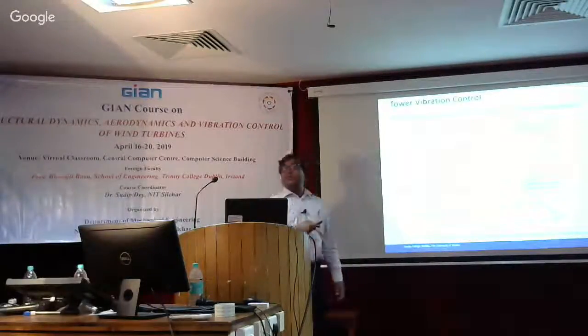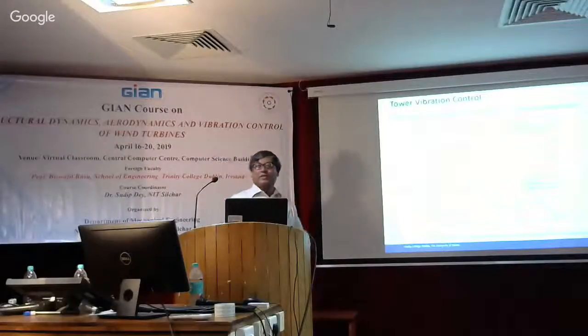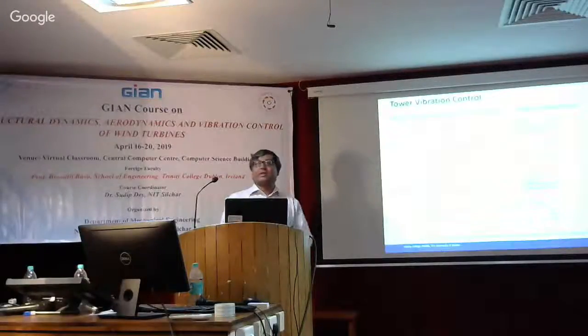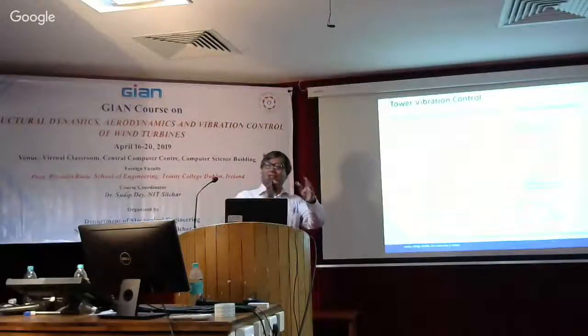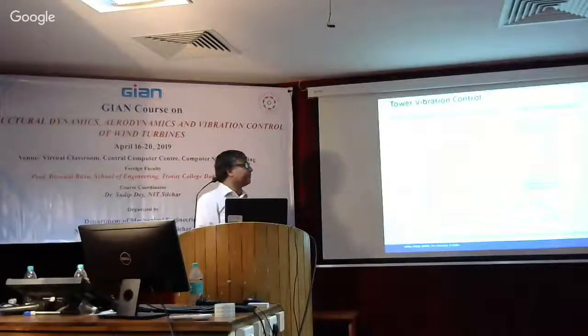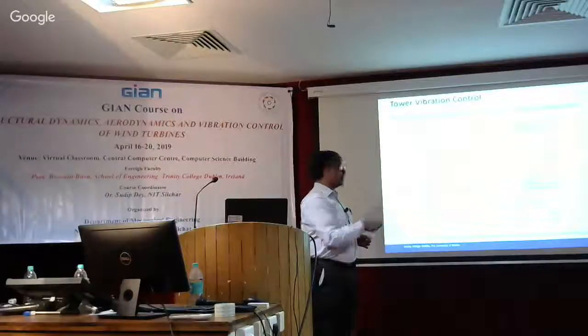So here you see the target displacement and the measured actuator displacement. You can see that they're almost accurately matching. This is because we're not measuring, computing and then sending that signal, but we're using discrete transfer functions with delay compensation with the controller. This controller is not the controller for the vibration, but the controller for the control of the experiment itself. But you're right, this is an important point. This shows that delay compensation is taking place in this case.